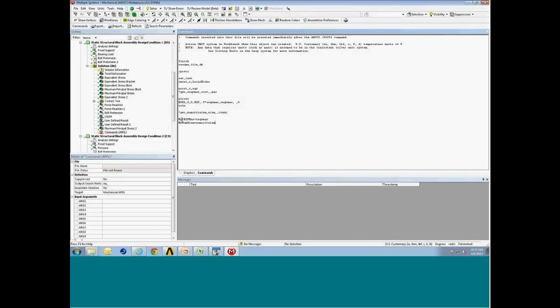We can also send these particular parameters out to Mechanical by identifying the output search prefix to take the parameters calculated and send them to the Mechanical tool within Workbench. So I'm going to use this as a filter called anything starting with MY. I'm going to filter that out and send this back to Workbench.